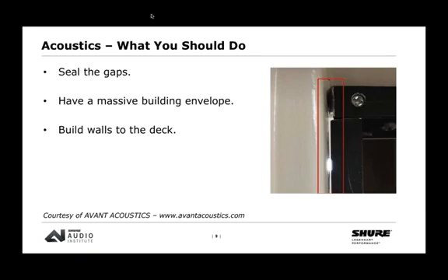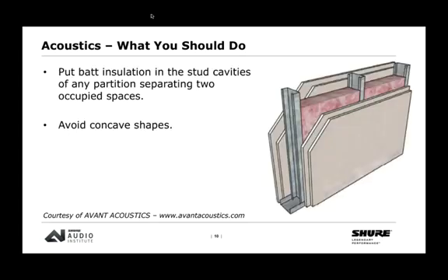So what this refers to is many conference spaces have drop tile ceiling, or maybe there's a void to the ceiling above, even if there's not drop tile. But what happens is in the larger floor space, if all of the ceiling space above is open, potentially we have another space where audio or ambient noise can play into and get transferred into other rooms. So if we build the walls in those rooms all the way to the deck, this helps to stop unwanted sound from penetrating into other rooms around that one room.